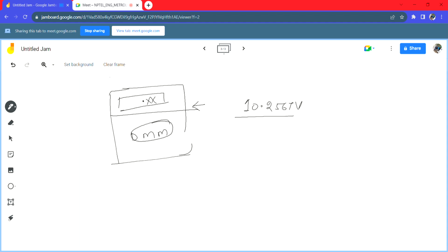So see, to better understand this, we have some values here which are not a problem for us in any of the cases. So anything above the decimal would not create a problem. Now, if this has a resolution of two digits after the decimal point, the minimum it can read is, say, 0.01, 0.02, and 0.03 and so on.